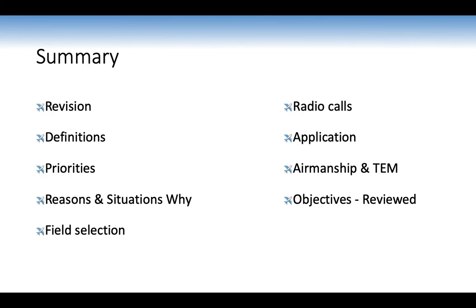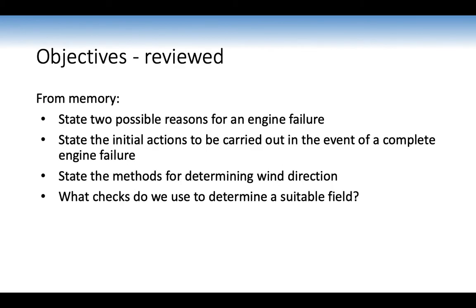We looked at the airmanship and threat management considerations, so the threats that exist and how you can mitigate the risks. In terms of threats, we look at traffic, minimum altitudes, warming the engine, and monitoring fuel. And make sure you aim to do the PFL over a non-populated area, for noise abatement, so we can go around at 800 feet instead of 1300 feet. And then finally, the objectives.